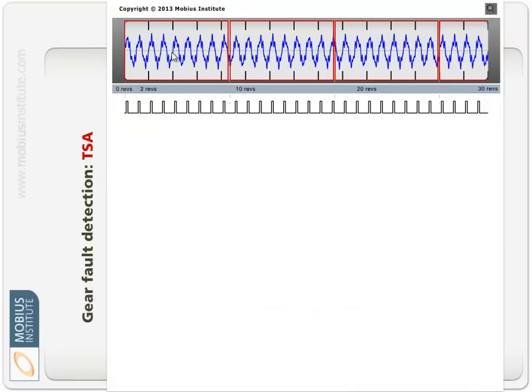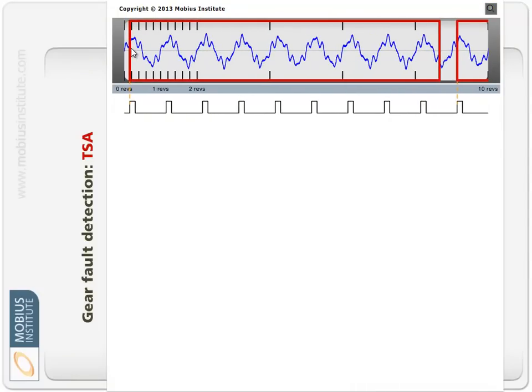And the difference is that when you press the go button, the analyzer will say, okay, I'm going to start digitizing internally, but I'm not going to save the data until I see a tach pulse come along from the shaft of interest. So the tach comes and says, oh good, let's go. And it grabs our 2048 time samples. And when it finishes, and during that time there'll be a certain number of revolutions of the shaft, rather than capturing this data as well, it says, wait, bang, there's another pulse that's come from my tach signal. Start saving these samples again, and it'll go again.